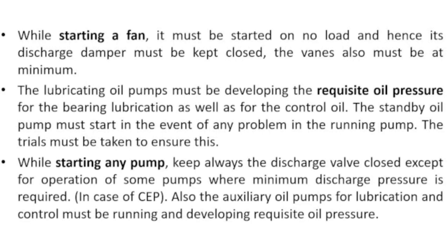Now when you start a fan, it must be started on no load and hence its discharge damper must be kept closed. The vanes also must be at minimum position. The lubricating oil pumps must be developing the requisite oil pressure for the bearing lubrication as well as for the controlling of the vanes, that is control oil. The standby oil pump must start in the event of any problem in the running pump. The trials for this must be taken to ensure this.